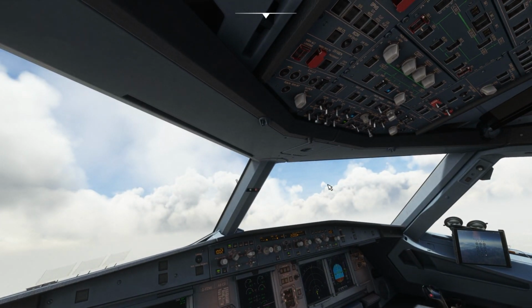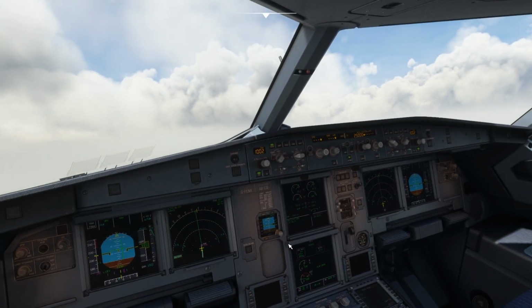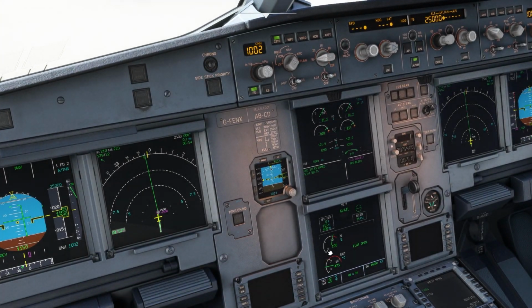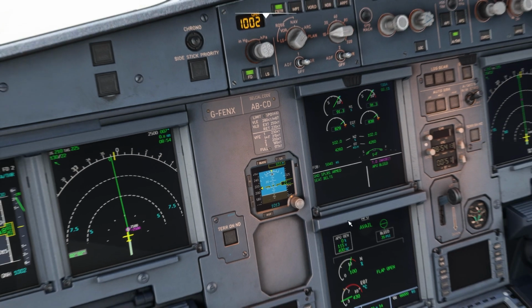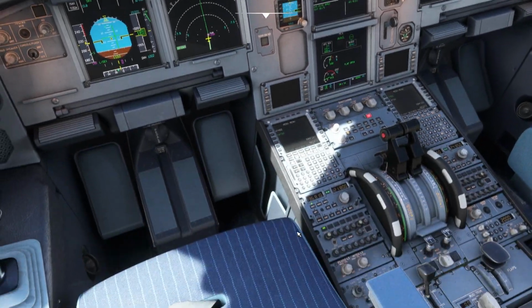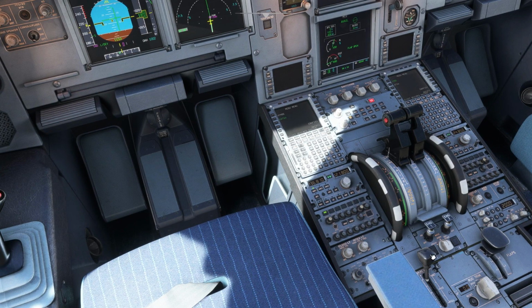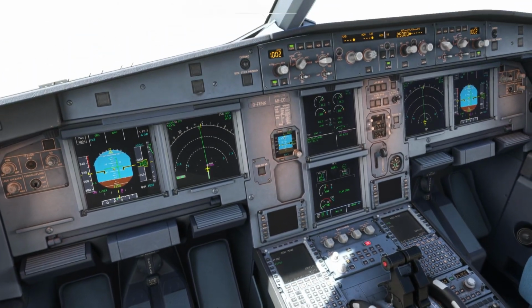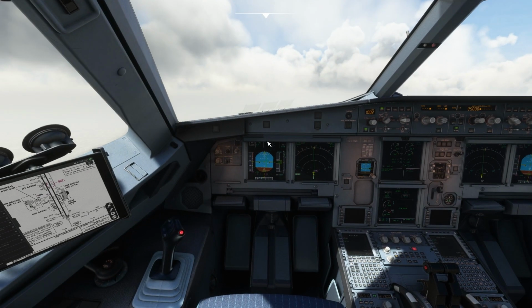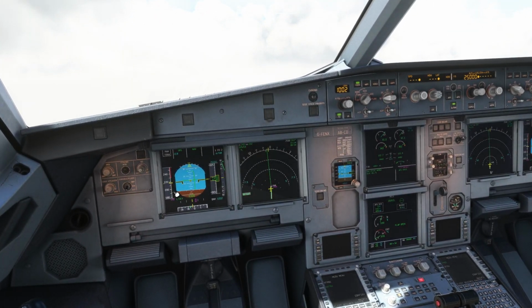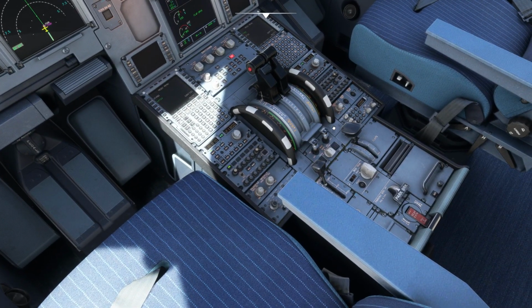Okay, so during the takeoff I forgot to turn off the APU bleed. See, the flight warning system, it happens. Anyhow, as I'm talking, there are so many things going on, that's why it's better to have a look at the flight warning system. So you have to set the flaps to 0. Okay, so let's play the simulator, and as I've crossed the S speed, I will take the flaps to 0.